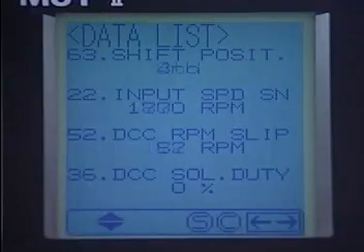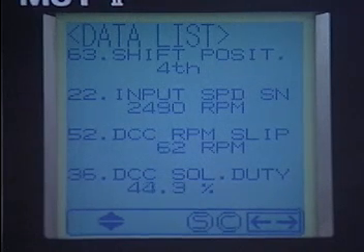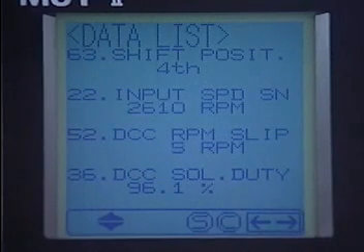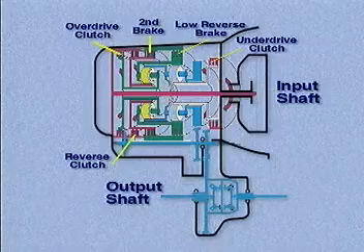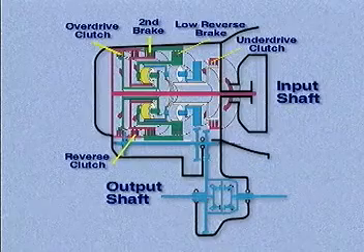Damper clutch operation is similar to previous automatic transaxles. The damper clutch has a dedicated control solenoid. Unlike other friction elements, due to the design of the damper clutch pressure control valve, the damper clutch is applied when the damper clutch control solenoid valve is on. Now let's take a look at power flow and elements in use during a series of shifts.